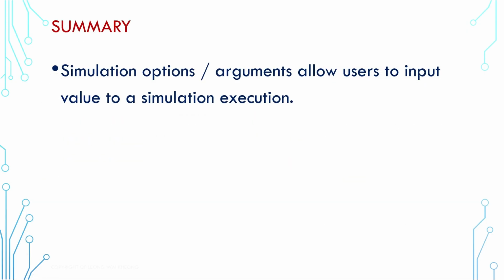In summary, we use test plusargs and value plusargs to provide a user value to a simulation. And this provides a greater control for the users. Apart from selecting which value, users can also select which test or which sequence to be run.